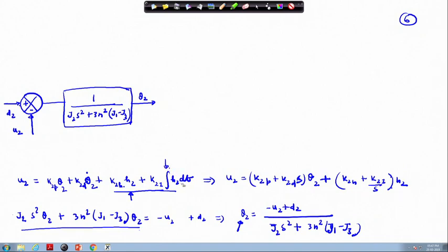As you know, the integral control is used for removal of the steady state error. So, you can use it for the control moment gyros momentum hold, or you can use it for the attitude control. Both are possible in this mode.